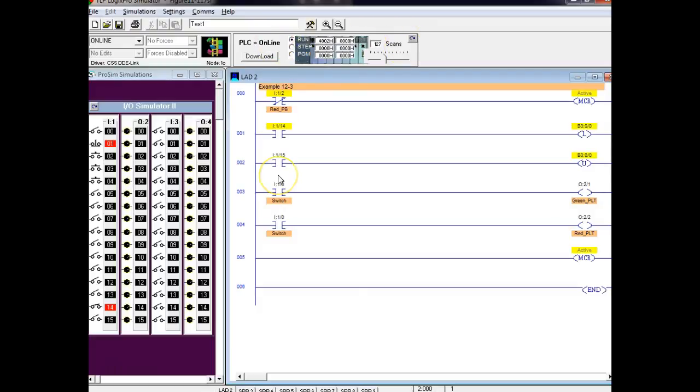Now it's okay. But the problem is, MCR is active, so it's scanning over the rungs. Everything's fine, but I had to use a normally open push button. Do y'all understand that? OSHA says you can't use a normally open push button for an e-stop.